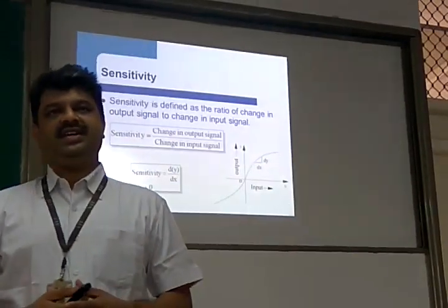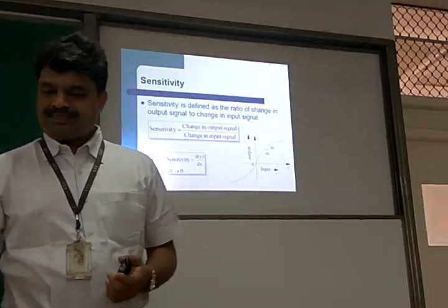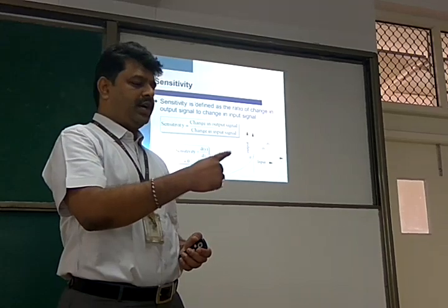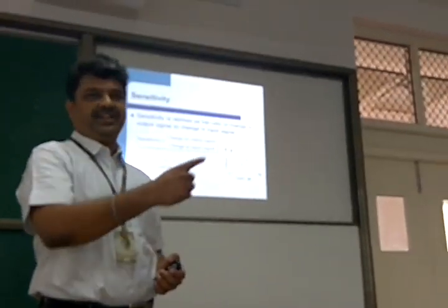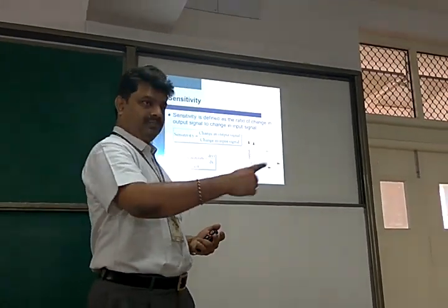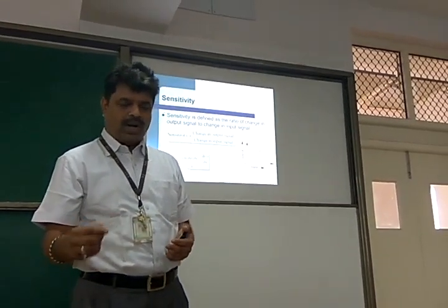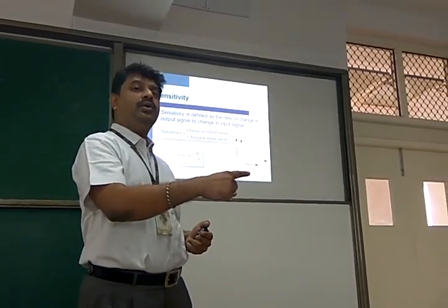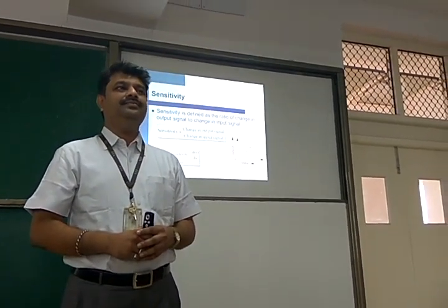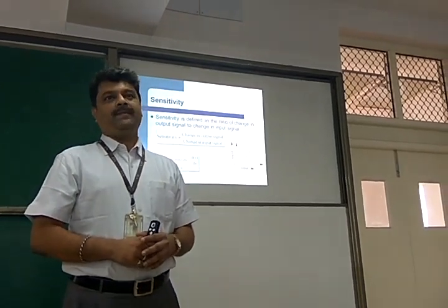What is dy? What is dx? That becomes sensitivity. You give 1 psi pressure in the quadrant tube. You want to know how much deflection there is. If you give 1 psi and there is a 5-degree shift in an angular term, and you give 1 psi pressure and there is a 2-degree shift, which is having more sensitivity? 5-degree shift or 2-degree shift? 5-degree shift.